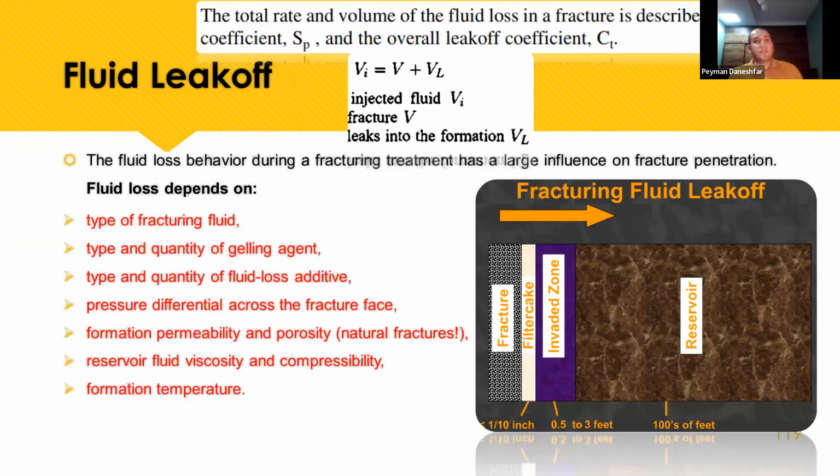One of the parameters that I mentioned before is fluid loss, and the fluid loss additive, and another thing, fluid leak-off. What is fluid leak-off? As you can see here in the picture, when the fracture creates a filter cake in the wetting zone and the reservoir, the fracture goes inside the reservoir and gives us leak-off of the fracturing fluid.